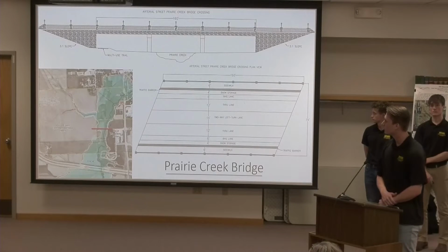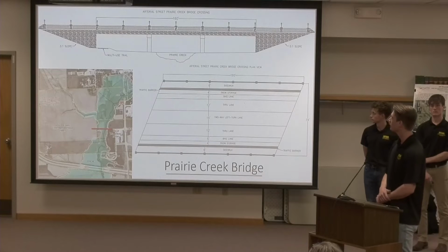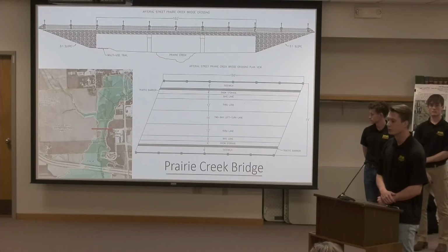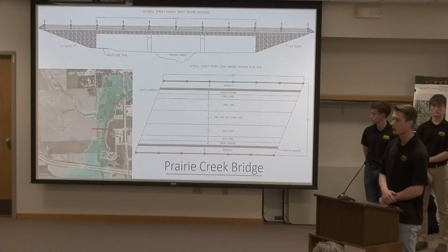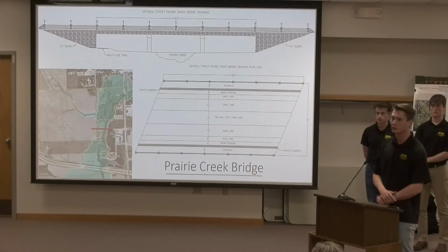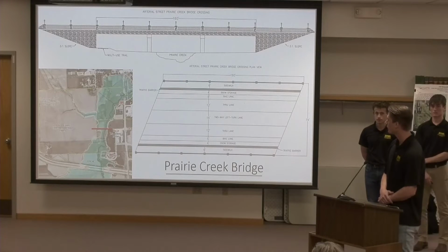The bridge will be a triple span concrete deck bridge with 2 piers and vertical abutments that will allow for minimizing the span length. The deck will be a continuation of the lane configuration of the commercial area, and will have bike lanes and snow storage, and will also contain sidewalks on both sides with a traffic barrier.